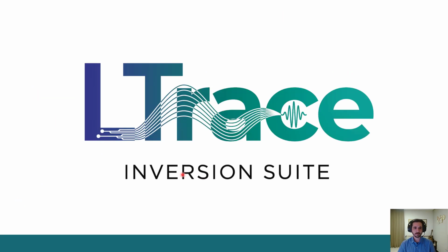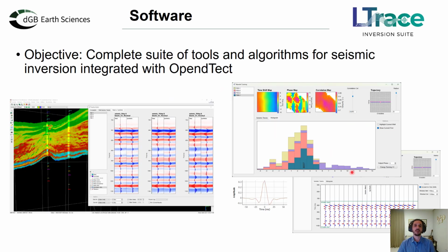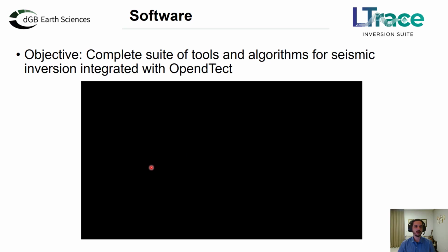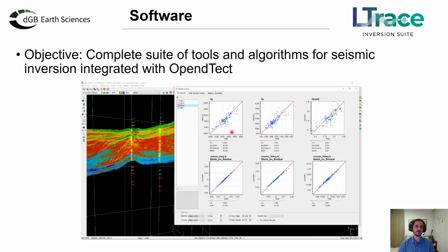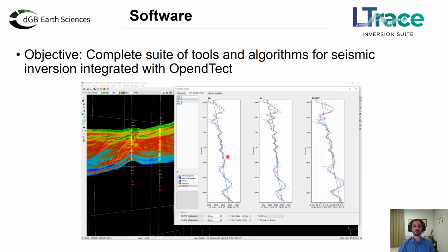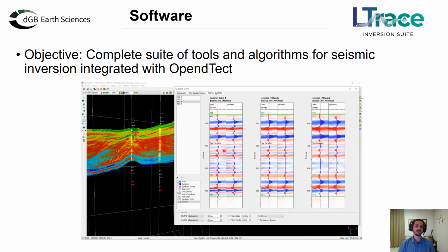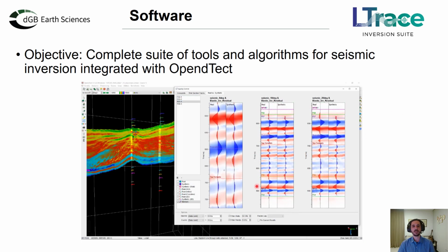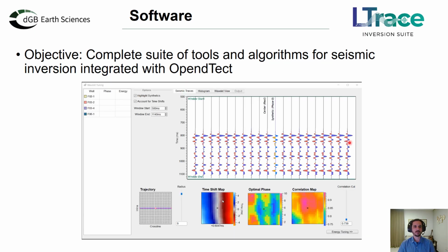So about our plugin, the main objective is to provide a complete suite of tools and algorithms for seismic inversion integrated with OpendTect. And here I have two short videos showing a little bit about the interface, where you can make the quality control of the inversion comparing to the well data, and also the angle stack seismic data around the wells, and also our new wavelet estimation, multi-trace, multi-well wavelet estimation.